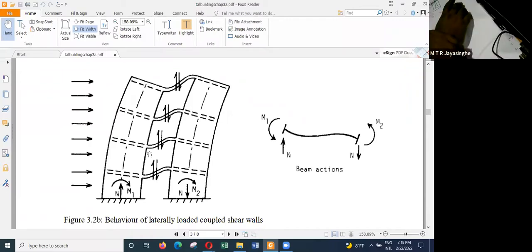So you can see coupled shear walls could be very helpful. And the moment you couple two shear walls, the overall shear wall length is something like 7-8 meters. They're huge, strong shear walls. And then the coupling beam also can be something like 300 millimeter depth, and it can go up to about 800 millimeter, 900 millimeter.